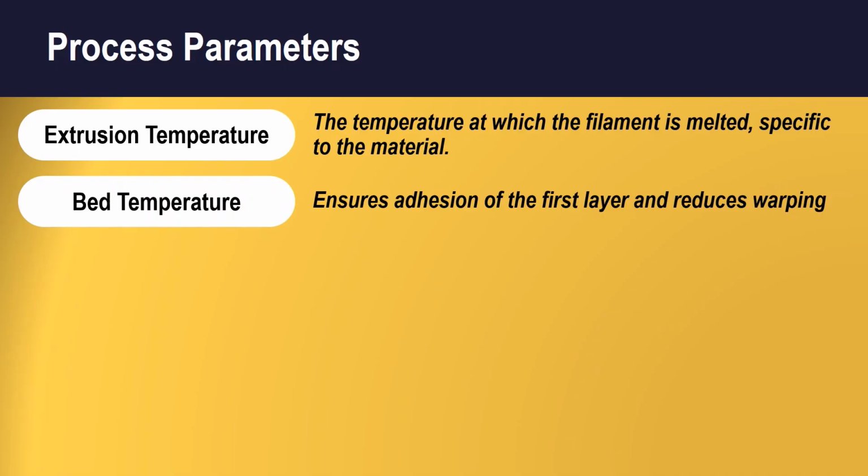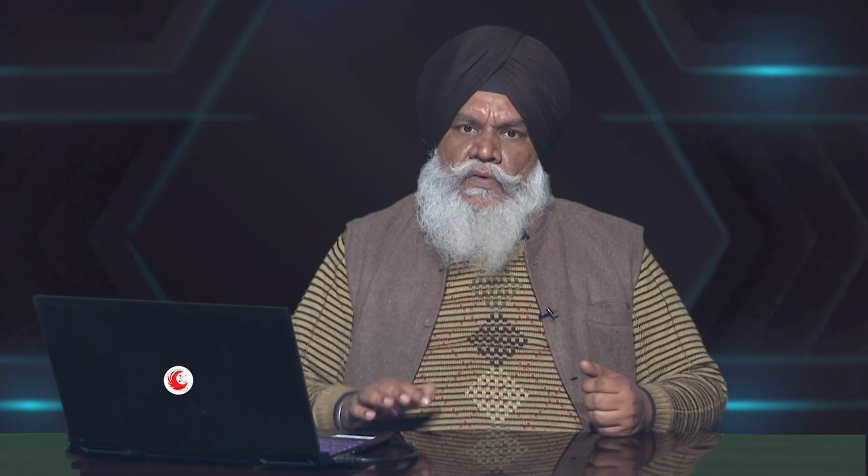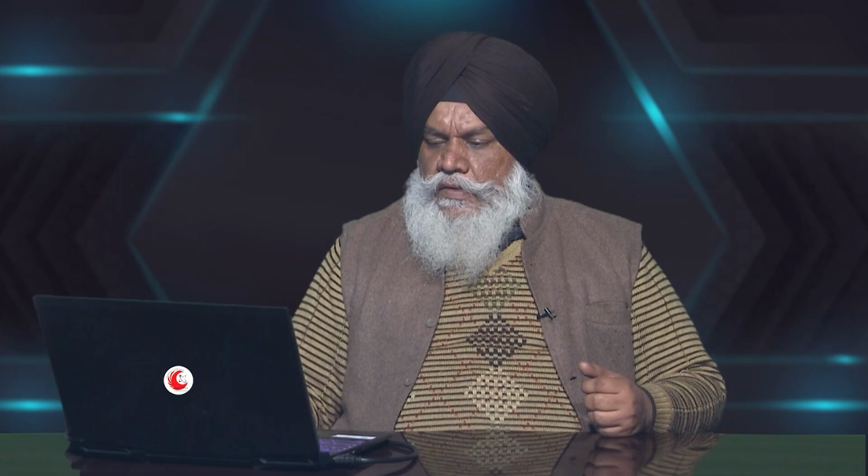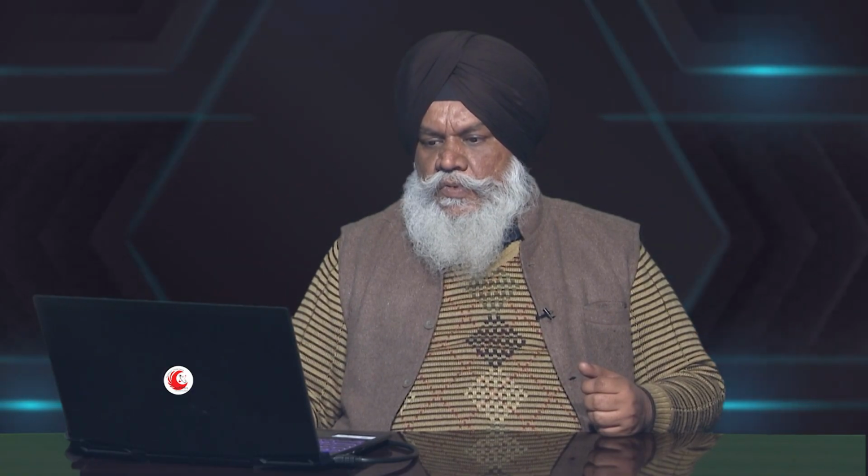So depending upon my application and the filament I select, I work over the extrusion temperature. Then there is a parameter called bed temperature. This is of course important to ensure the adhesion of the first layer. For the bed temperature, again different types of plates I am using. It may be glass, it may be metal. This is important because first layer adhesion is very important, as it reduces the warping of my functional prototype.